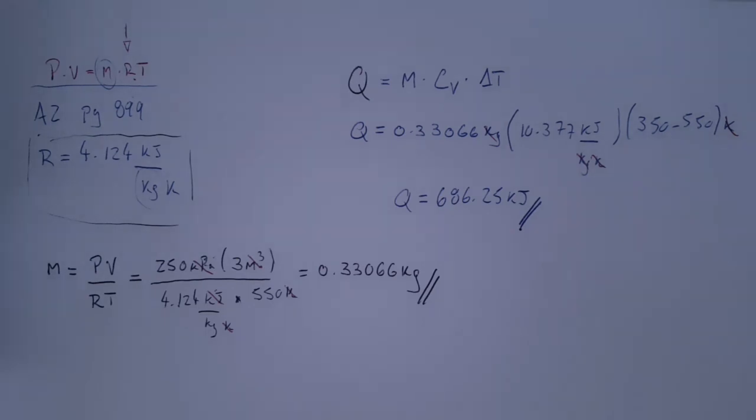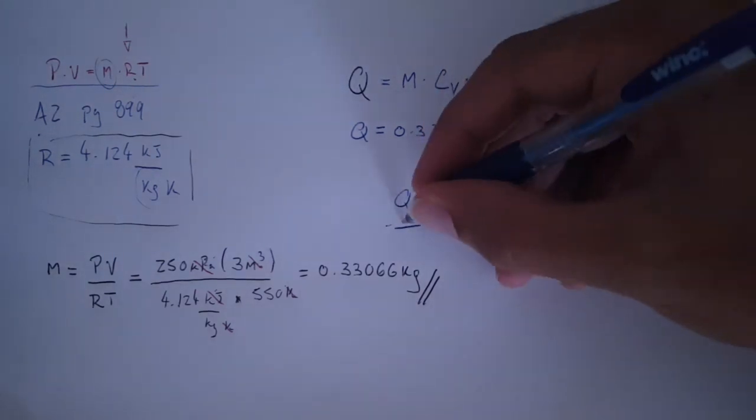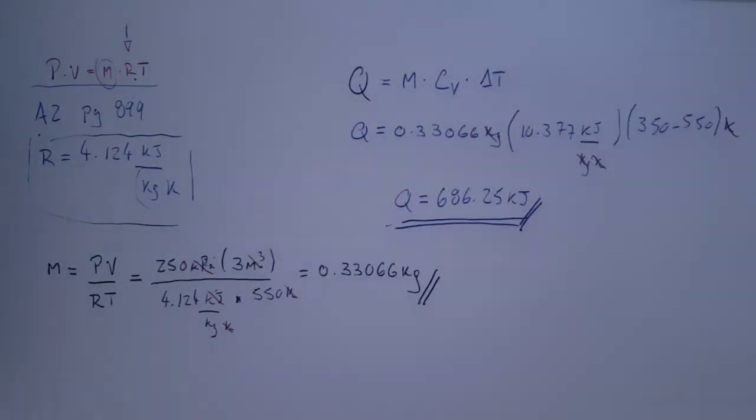Okay? If you didn't use bulk temperature, if you got CV for the first state, for instance, you're going to have something similar, like 673. So watch out. It depends on what your assumptions are. You're going to have a slightly different value. This, in my opinion, is one of the best ones in terms of minimizing the errors that you can have while using the tables. Okay?